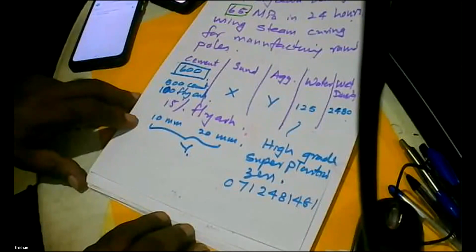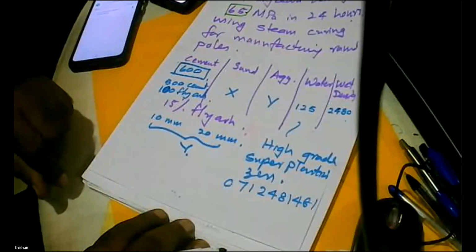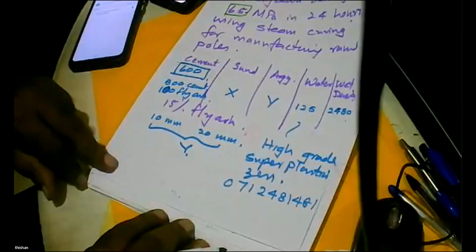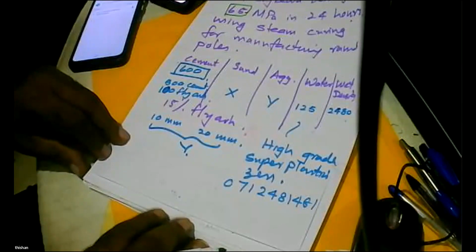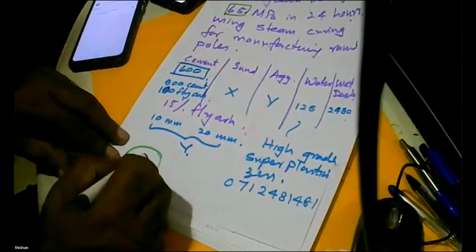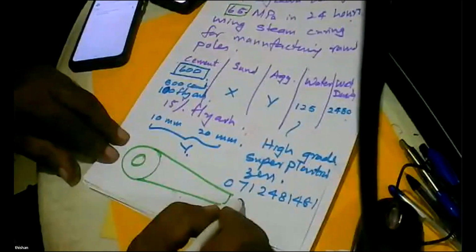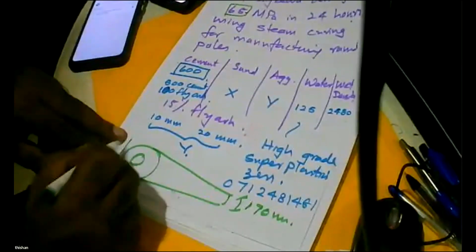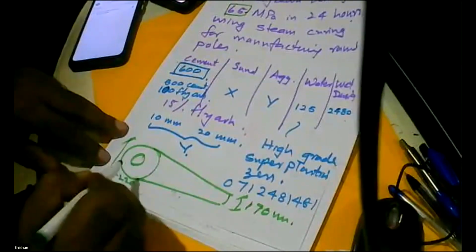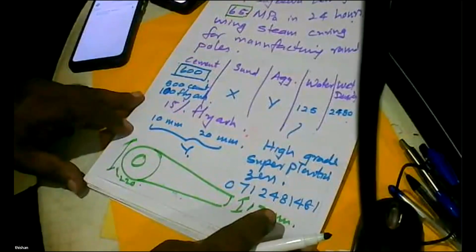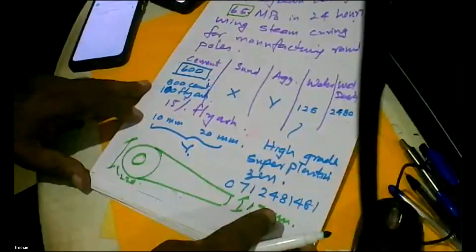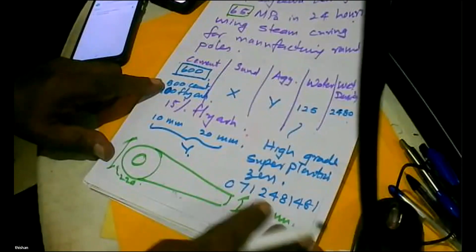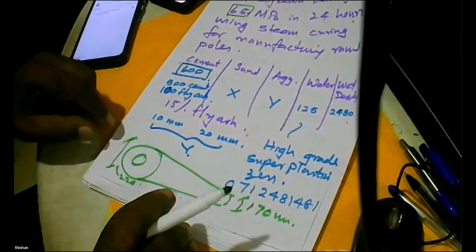So it's good to have something like 600 cementitious material, not cement, but cementitious material. And because these are very small poles, hollow poles, on this side it may be about 170 millimeters, here it may be about 220 millimeters, very small. So you don't have to worry about DEF due to high cement content, but when you are doing the steam curing, you have to control the temperature. Now let's look at what I did.